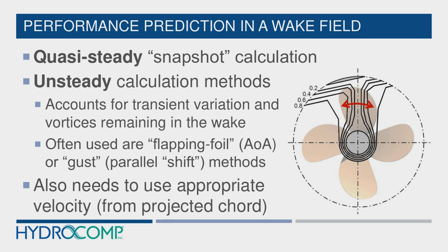Well, a couple of key takeaways to think about: the forward half of a propeller or any airfoil does most of the work. One of the attributes of foils is that the center of motion, or the center of forces, is at the quarter chord length.